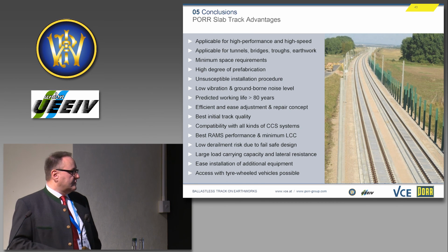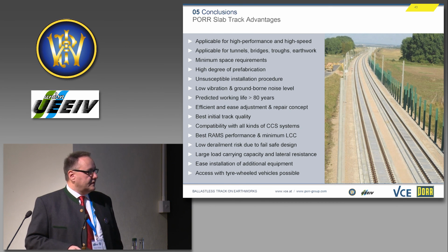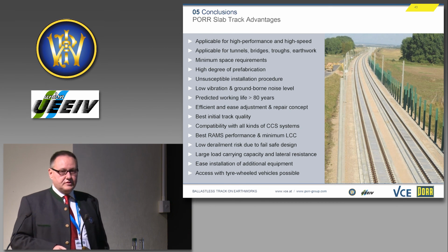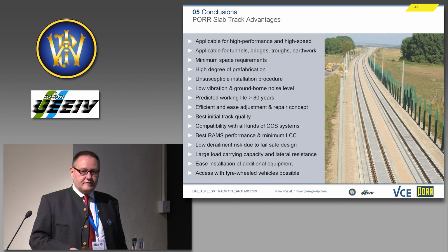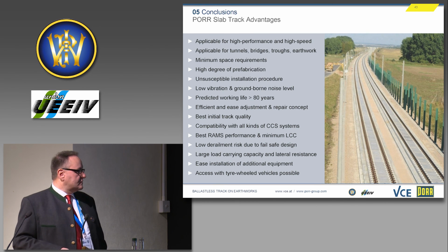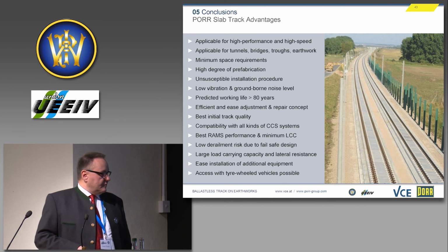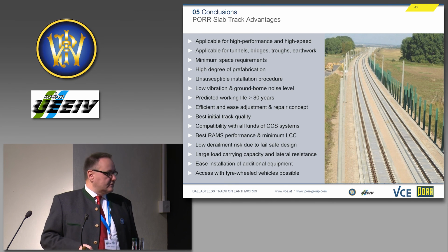And we have an easy installation of additional equipment due to the fact that it's only a reinforced slab and not pre-stressed, so it's allowed to drill everywhere on the slab for additional installations. And we have accessibility with rubber-tired vehicles.